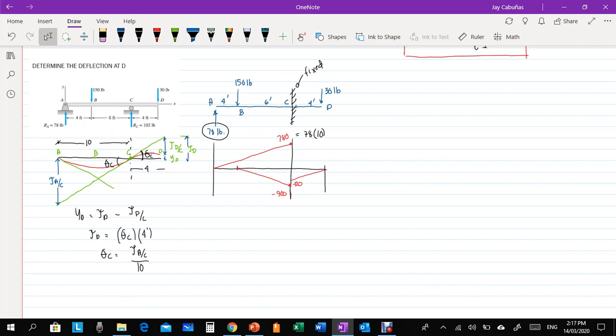It is triangular. Since our shear diagram is zero degree, therefore the moment diagram is second degree. Now, 150 pound, the 150 pound is this one. That is just 150 times, what's the moment arm? Times 6. Okay, how about the diagram at the other side?